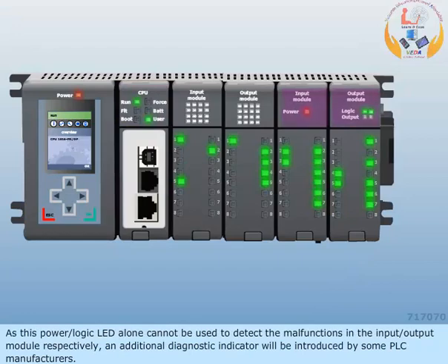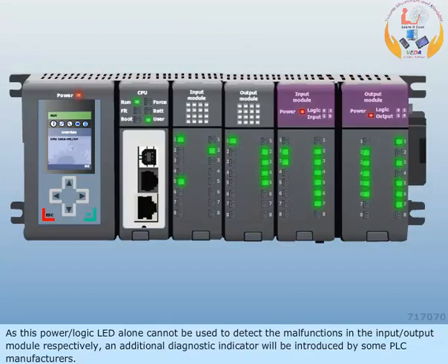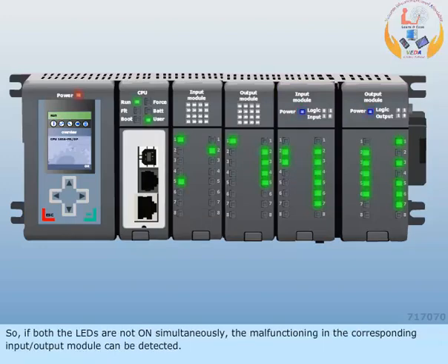As this power or logic LED alone cannot be used to detect the malfunctions in the input or output module respectively, an additional diagnostic indicator will be introduced by some PLC manufacturers. So, if both the LEDs are not on simultaneously, the malfunctioning in the corresponding input or output module can be detected.